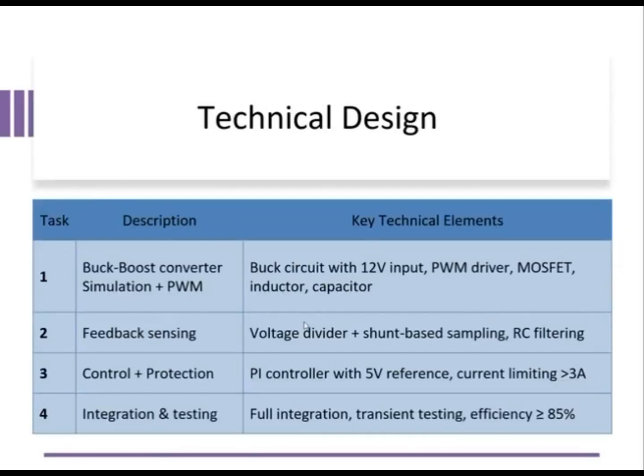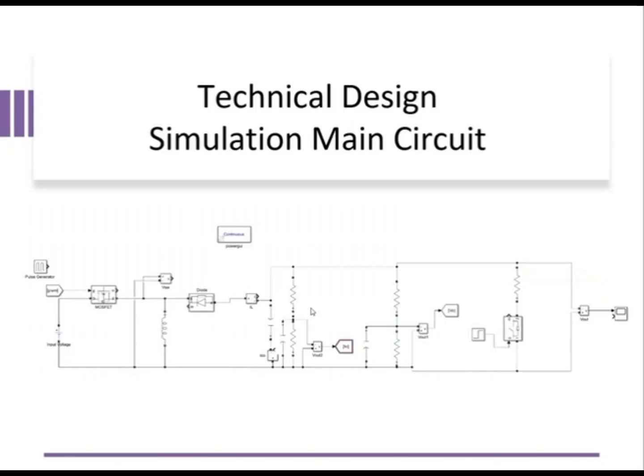Next, the technical design. I've divided it into 4 tasks. I'm in charge of the buck-boost converter simulation, which consists of the input, PWM driver, MOSFET, inductor, and capacitor. The PWM driver controls the switching of the MOSFET, and the inductor and capacitor work together to achieve voltage conversion, which is the foundation for the entire circuit's operation.